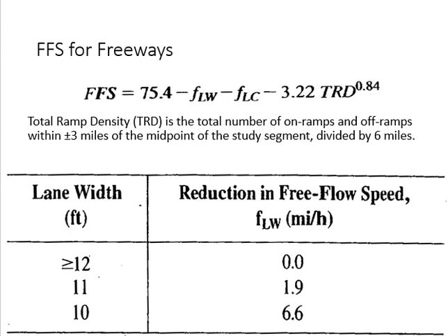Distance over time. What do we call that study? Spot speed study. So this is one method of finding out free flow speed, which you already did. If you didn't do it, then we have equations to find it out. If you did the spot speed study, that becomes your free flow speed. That's it. No other calculation required for the free flow speed.